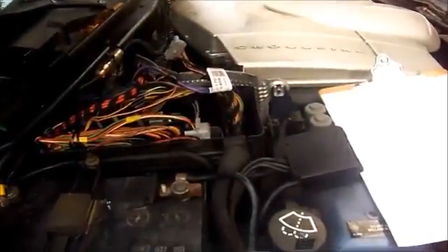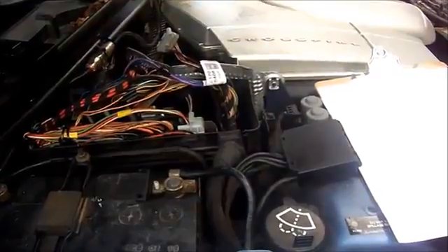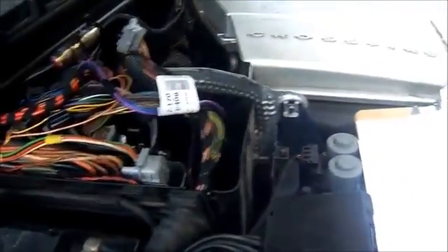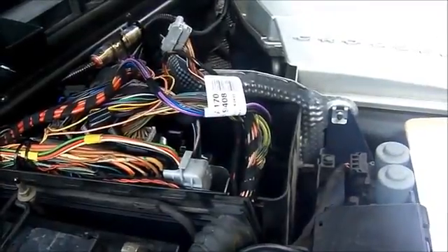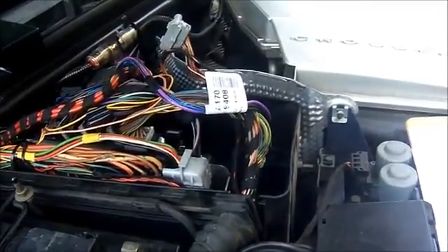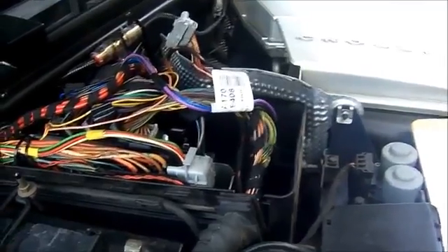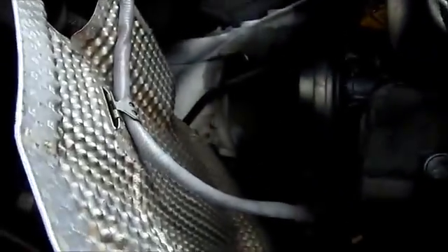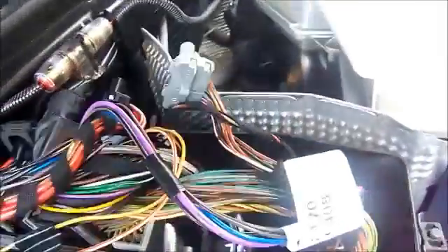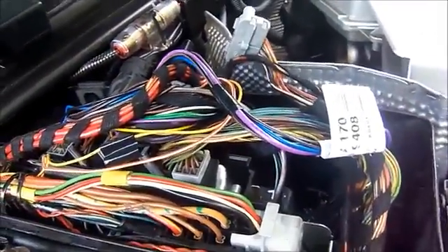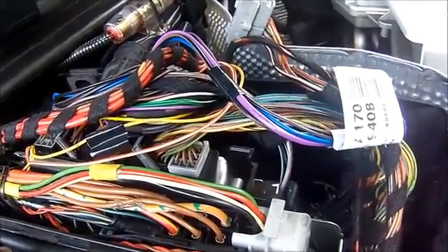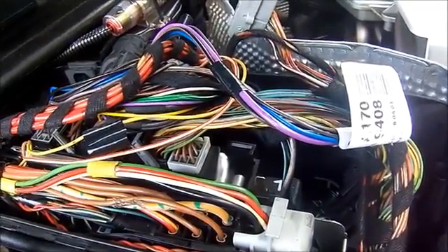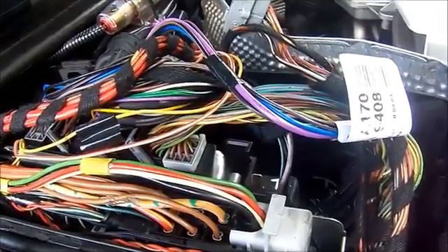What I have here is a 2005 Chrysler Crossfire, and our transmission is in fail-safe mode. We have a P0753 shift solenoid A electrical, and they replaced the connector that goes into the transmission, and it was leaking fluid out of there. We have no communication with the powertrain control module and no communication with the transmission control module, but we do have communication through the OBD2 direct, and that's where we're getting our code.